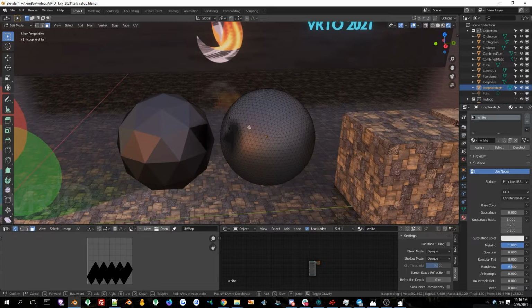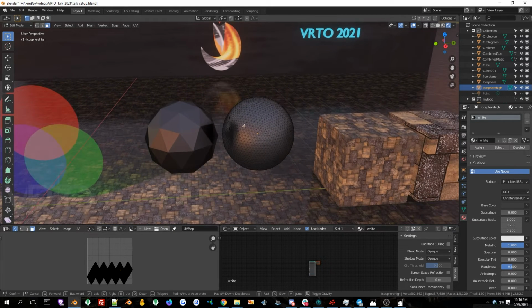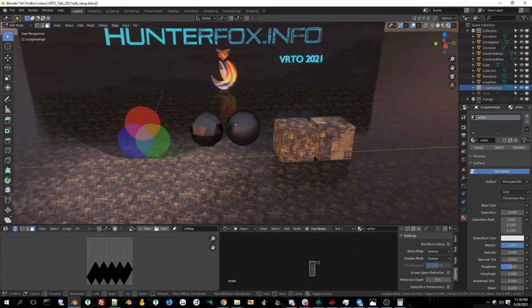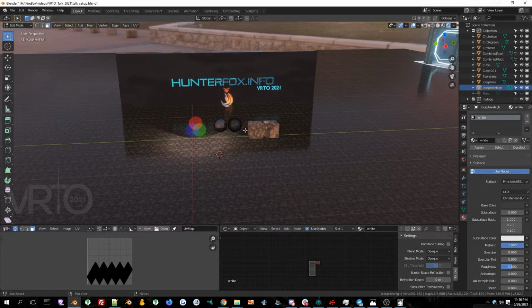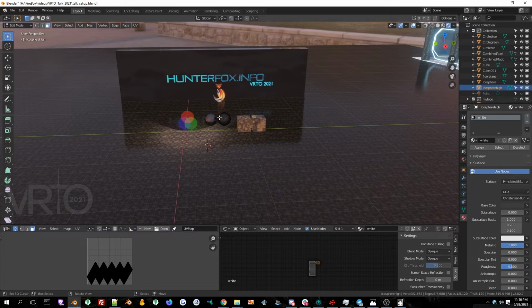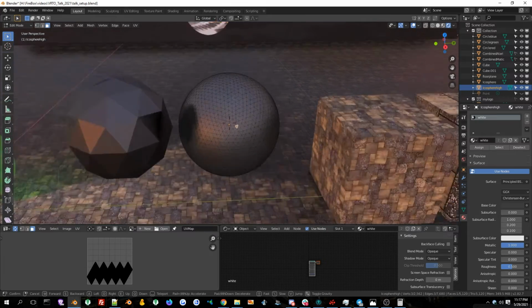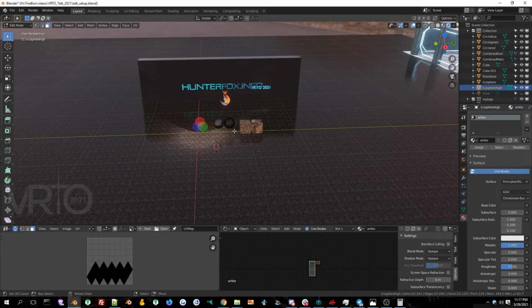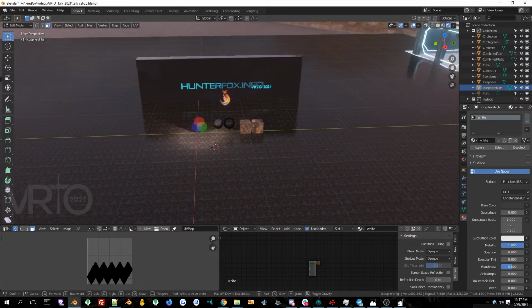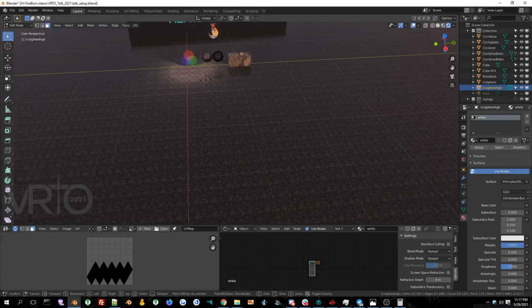Now, subpixel texel rendering means that at a certain distance, a single polygon or mesh section, a texel basically, is going to become smaller than a pixel, and your computer actually has to work much more to sort that out and display basically a nearest neighbor type situation. So you want to avoid having any mesh that is smaller than a pixel at any level of distance.